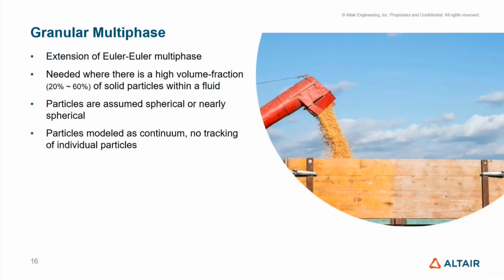Based on the Euler-Euler multiphase feature, and actually an extension of it, is granular multiphase. I mentioned before that the solid dispersed phases could be used with Euler-Euler. When the volume fraction of those particles becomes high, say about 20% or more, additional physics need to kick in. This is what's included in the granular multiphase feature.